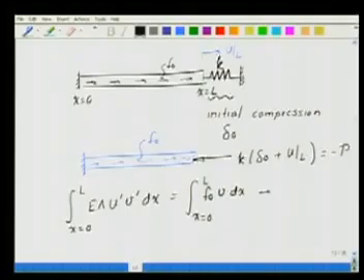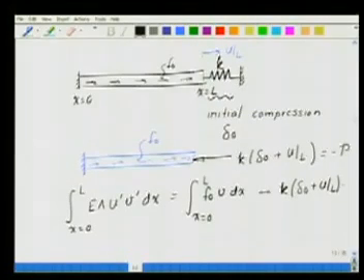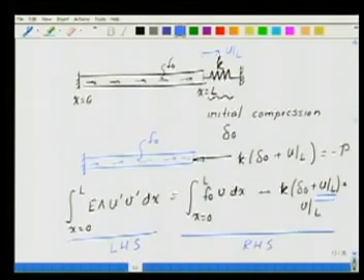So I will write minus K delta naught plus U at L multiplied by V at L. So this is the weak form we get. Now you see there is something very curious about this weak form. This unknown U at L, we had said that in the weak form we are going to collect the unknowns on the left hand side and the knowns on the right hand side. But you see that in the right hand side now even an unknown U at L is sitting. So what do we do? We shift it to the left hand side.